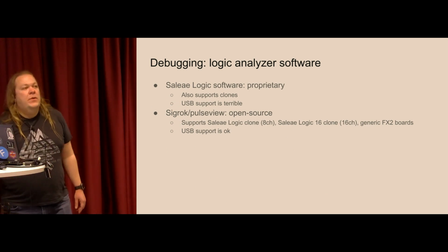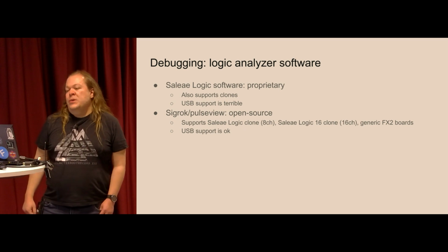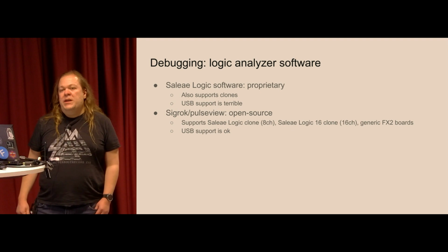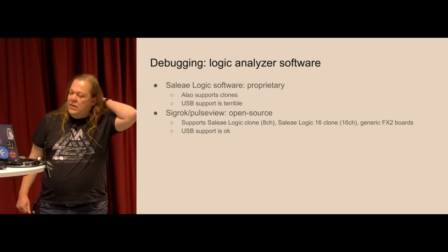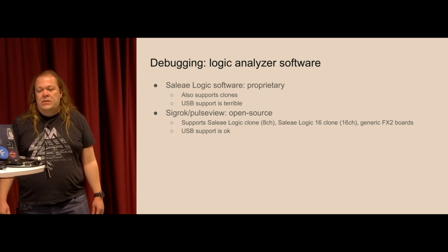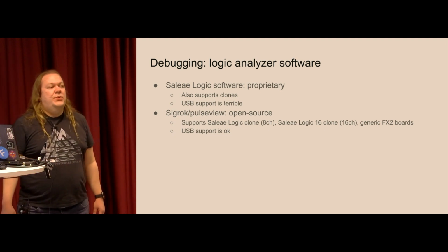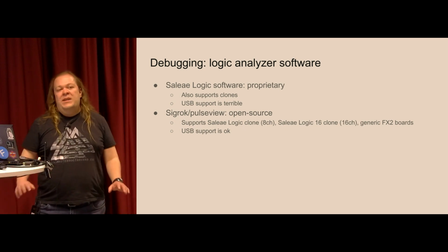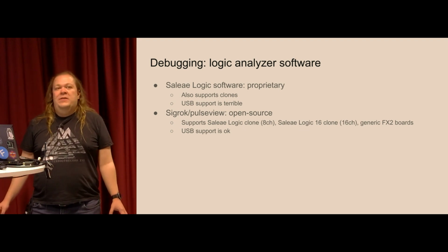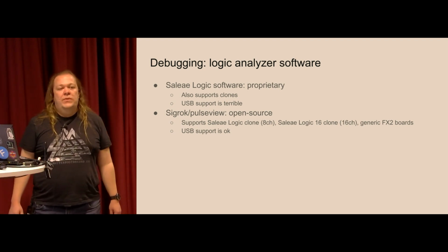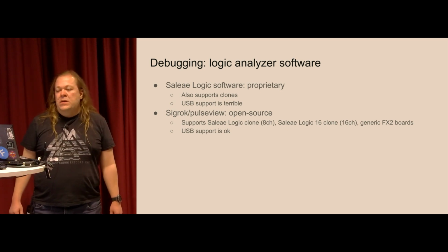As for the logic analyzer software, the situation is pretty poor, I would say, because we have official software from Saleae, which is proprietary, but it can be extended with some plugins, like decoder plugins, which is not useful for USB in this scenario, but it also has a decoder for USB, and this decoder is quite bad, I would say, because sometimes it just fails to achieve a lock on the data it fetches, even if this data is fetched at the very high speed, like maximum possibilities, but then it fails to acquire a lock and the decoded data is just wrong.